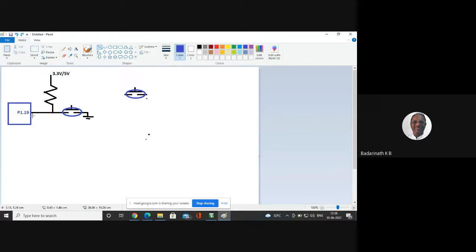So how do we produce that expected value here? That is where we use a pull-up resistor. If I don't use the pull-up resistor when I am not pressing the key, the line is just floating. It can pick up noise from anywhere in the surroundings, so the value you read may not be the true value, sometimes 0, sometimes 1, depending upon the noise. To make sure it's always stable, I connect through a resistor of 4.7K or around 10K to the voltage of 5 volts. Whenever I pull up like this, the voltage at this point is confirmed: I'm receiving 1 if I'm not pressing the key.